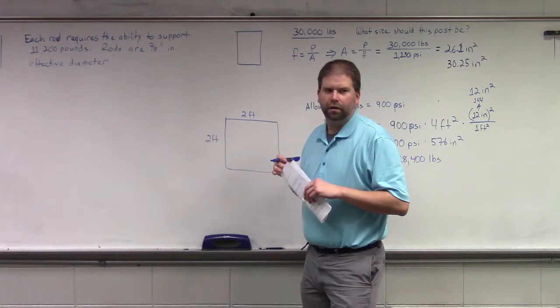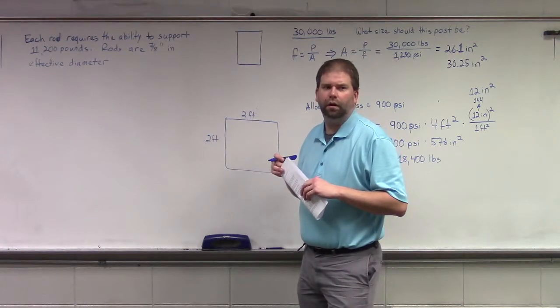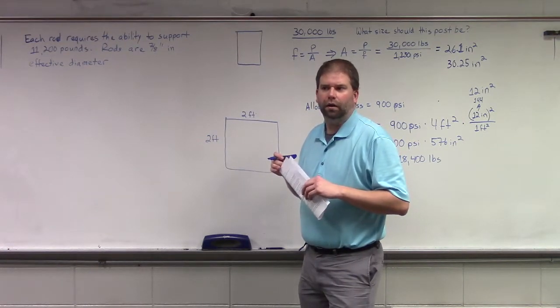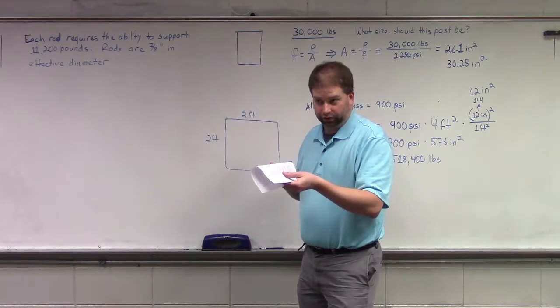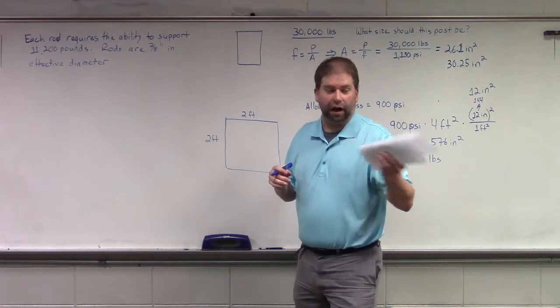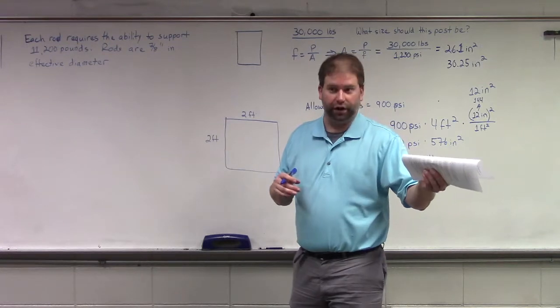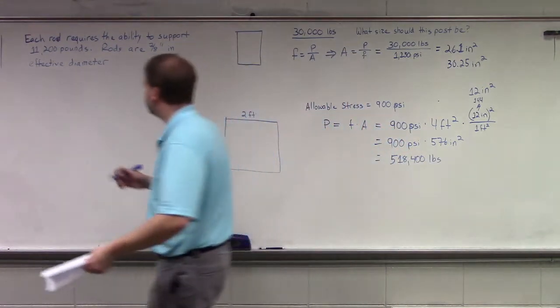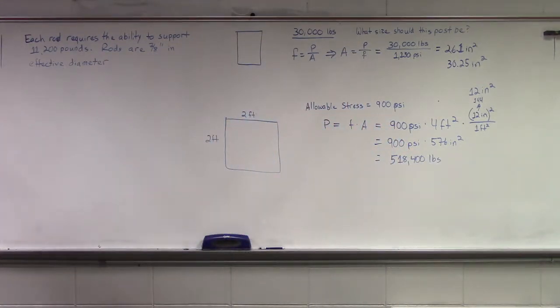No, you need to make sure it's less than the allowable stress of steel, 30,000. Careful, careful. Our allowable stress for steel is 30,000 PSI, pounds per square inch.